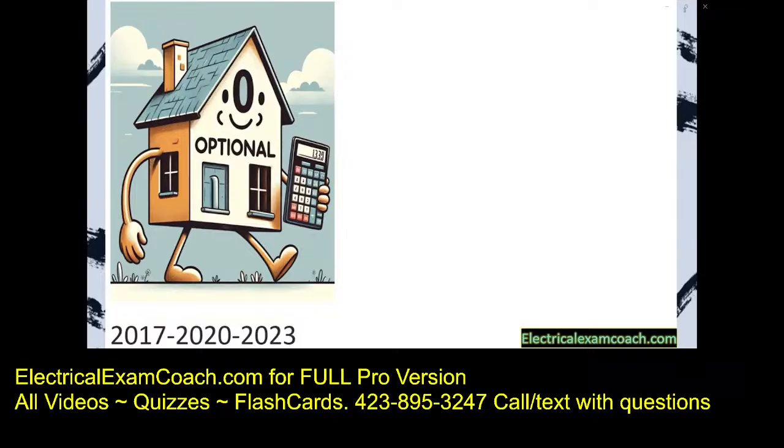In the absence of a method listed on your test, you're always going to default to the standard method. And thankfully, you'll never get an optional method question unless it states the words "using the optional method." It's so important that we know that. We're going to find all these rules laid out in 220.82. Specifically, we're going to be focusing on Part B.